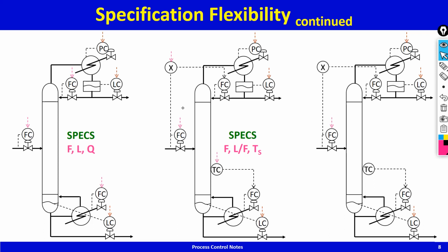Now I have the same control structure as in figure 2, sub figure 2, and now what we do is we put in two composition controllers. These composition controllers are shown there in the figure. Purity of the distillate is being controlled by this controller by adjusting the reflux to feed ratio.